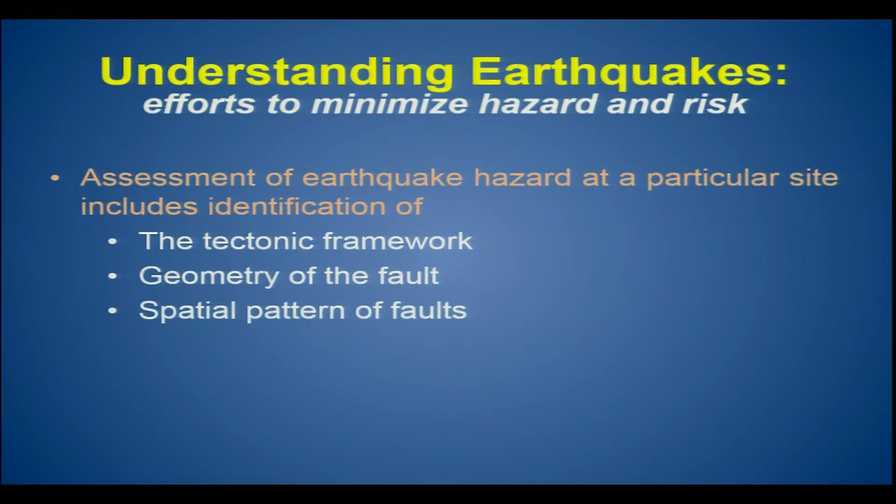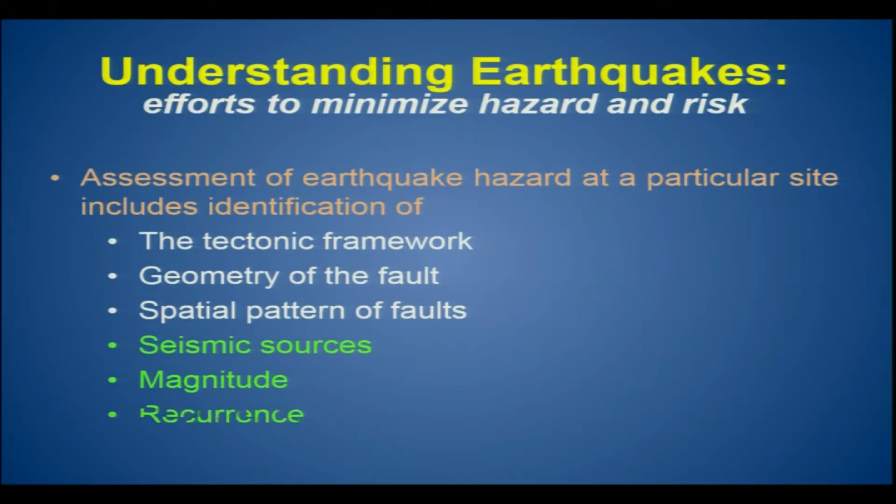And then comes the segmentation pattern of the fault, how it behaves along the strike and its extent. Then we talk about the seismic source, how deep the earthquake is, okay, and the magnitude of the particular earthquake, and the recurrence finally. So these are a few bullets which are, of course, important for the assessment of earthquake hazard at a particular site.